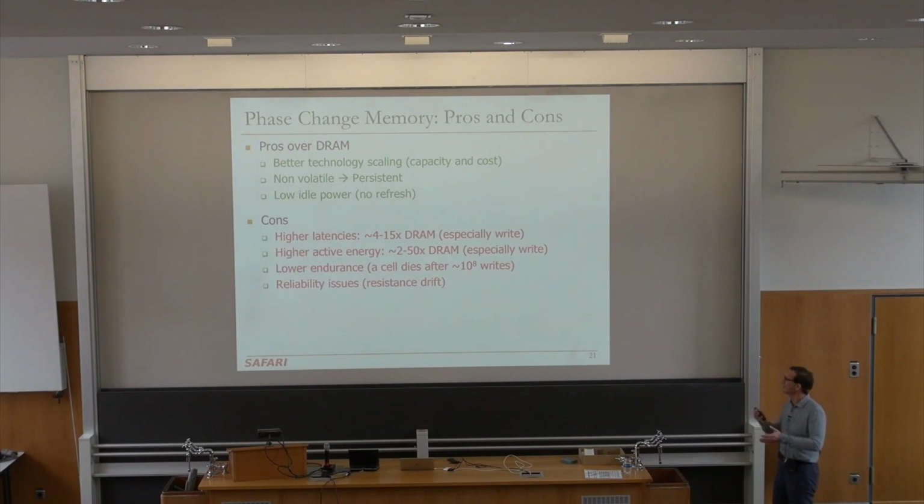You can guess, model, do circuit level evaluations, but as I said very earlier, even in DRAM, we do not know how to exactly model these issues. As a result, we're running into problems like row hammer, for example. So if you cannot do it in existing technologies, you can imagine that it's going to be orders of magnitude more difficult to do it with an emerging technology where you don't really have the devices yet. Right? So that's why we're going to ignore the reliability issues, but this doesn't mean that they don't exist. Actually, some of the reliability issues can threaten the existence of some of these technologies. Resistance drift is one example. As I mentioned, charge leaks, resistance drifts.